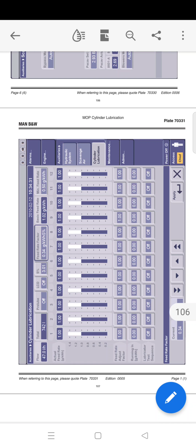If a single button, cylinder 1, 2, 3 etc., is pressed, a toolbar is shown on the screen. The toolbar enables the engineer to start lubrication on the particular cylinder concerned or on all cylinders. So guys, the lubricator test sequence can be performed for individual as well as all the cylinders, but the pre-lube button is used only for all the cylinders, and this is done during the starting of the engine, whereas the lubricator test sequence is done only for a single unit. So after maintenance we can press this lubricator test sequence for a unit where the maintenance has been recently carried out. The lubricator test can only be activated if the hydraulic pressure is present. This requires that the engine telegraph is put in the state standby or that the hydraulic starter pumps are set to manual operation and started.